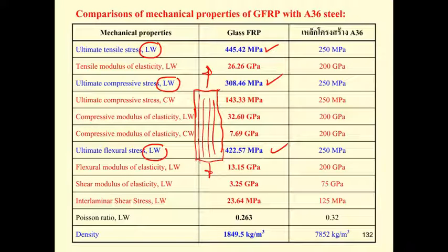fractional, okay, and the bad thing is they're going to get lower E. That's a lower E. So the design of this is similar to the aluminum. The modulus of elasticity is even lower than the aluminum. If you compare the aluminum before this, you have the E of about 70 gigapascal. And the steel, you got 200 gigapascal. But this one you can get only 26 gigapascal because it has the plastic cover with the fiber. So when it's plastic, the stiffness is going to be low.